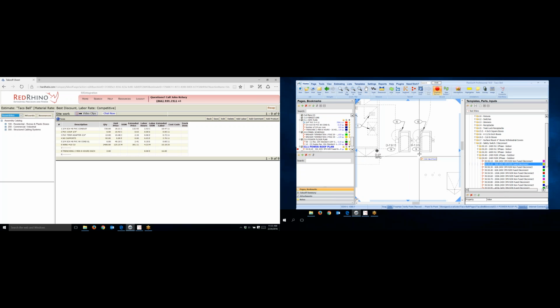And so I want to import, or I want to count these as assemblies, okay? These are my disconnect switches. I'm just going to click next to this one and this one. You can see it makes a mark on the page, but while I'm doing that, it's also counting on screen there. See how there's 2 of them on the cursor? And then it's also inputting them over here. See this? This is where it's inputting that disconnect switch.